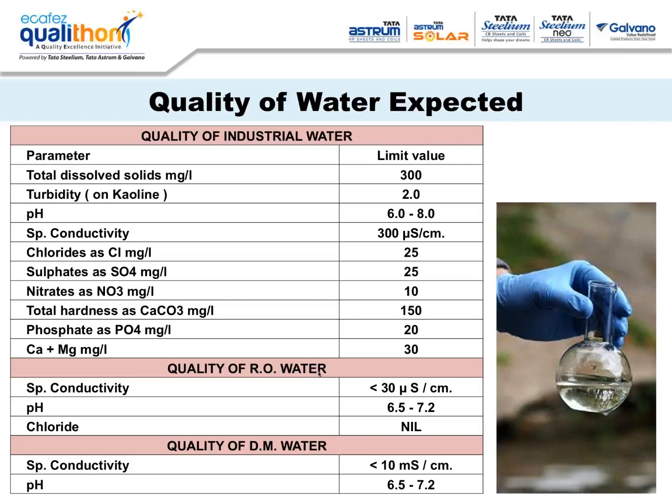The majority of the groundwater available in India has TDS of more than 1500, and I know certain places where the TDS is almost 3000 plus. If you use this water, there are going to be a lot of salts dissolved in it, and these water-soluble salts are going to give you trouble like blisters after the paint is cured or after it comes in contact with humidity, which we will be discussing in the next slides.